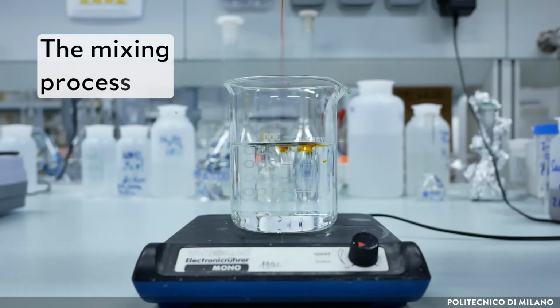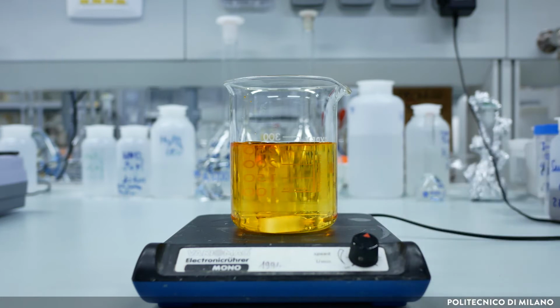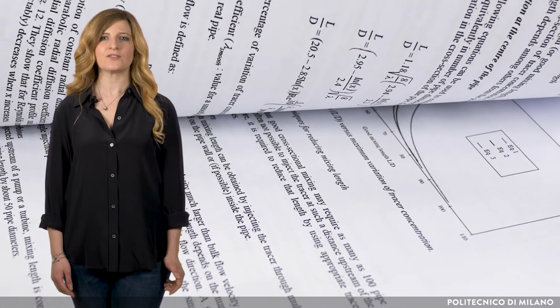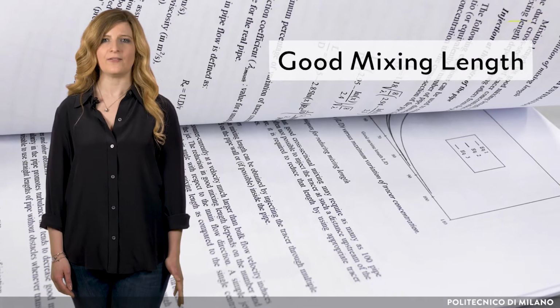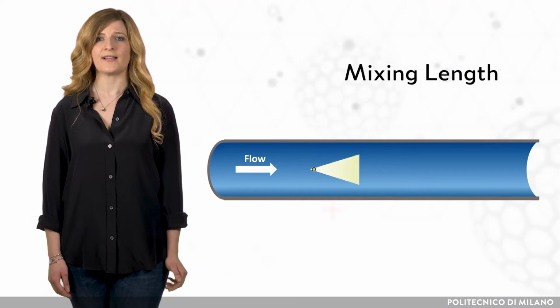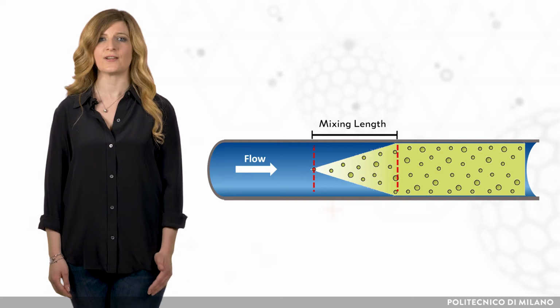It is very important to understand the mixing process. It depends on many factors: the position, the velocity of the injection jet compared to the bulk flow, the turbulence, the presence of turbines or pumps. Depending on the conditions, thermodynamic formulas are used, assisted by simulation codes. Standard procedures give the basic guidelines for the estimation of a good mixing length and suggest several means to reduce it. The mixing length in duct flow is defined as the distance beyond which the tracer concentration in the cross-section is almost constant.